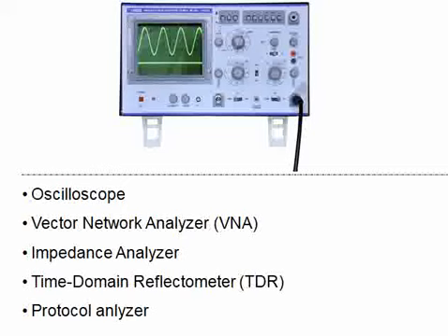Or if you take an RF signal, in that case, let us assume an interface working in the ISM band. If it doesn't work, how will you ensure? So in those cases, what we do is, during the design phase itself on the PCB, we do include some traces which are called the test coupons.